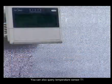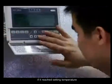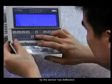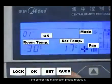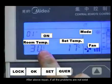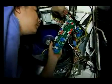You can also query temperature sensor T1 from the indoor central controller to see if it has reached the setting temperature. Check if the temperature data collected by the sensor has deviation. If the sensor has malfunctioned, please replace it. After the above repair, if the problem still exists, the indoor PC board may be broken, and you can replace it.